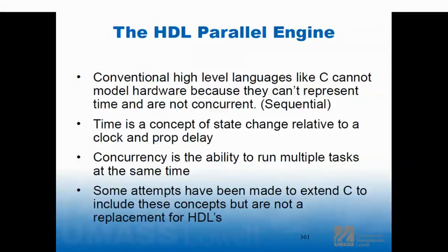So the first answer, and I'll pick the easy one, is you only have 1 clock. So the behavioral model that generates your clock, and you've seen it a bunch of times now, you saw it in the RTL class, you saw it here, it's inverting. That is the clock for everything. And now when you go through your tests, even though it's a sequential test, you're gating it, don't gate it by putting in times. So you see, pound 40 or pound cycle or whatever it is. Don't do that. Say @(posedge clock) within your tests.